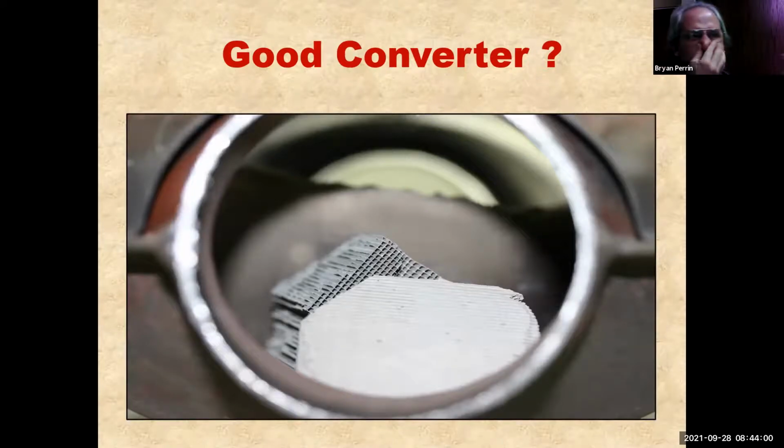But no, this was an original converter. So yeah, I think it had an event. But it is striking to me how it could pass so many tests, including the OBD2 monitor, with a third of the converter missing, and I'm looking right through it to the wall behind where I was taking the picture. And you know, that's kind of a lesson. Don't trust OBD2 to find everything for you. And also that all tests are not equal. Some are clearly better than others.